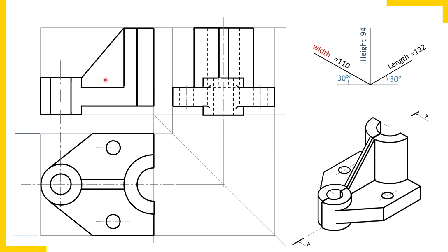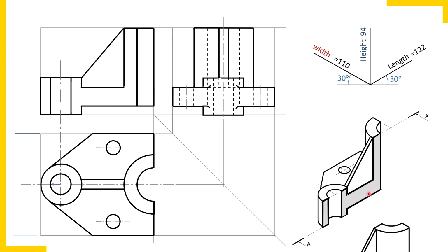So as I told you in an earlier video, when largest portion of a plate appears in sectional view, then you should assume that plate as uncut plate. Watch now this three-dimensional diagram. Cylinder is getting cut, semi-cylinder is getting cut. Likewise, this trapezoidal plate is also getting cut. Thickness of the trapezoidal plate is 10 millimeters, and trapezoidal plate also getting cut, so its thickness has reduced now.